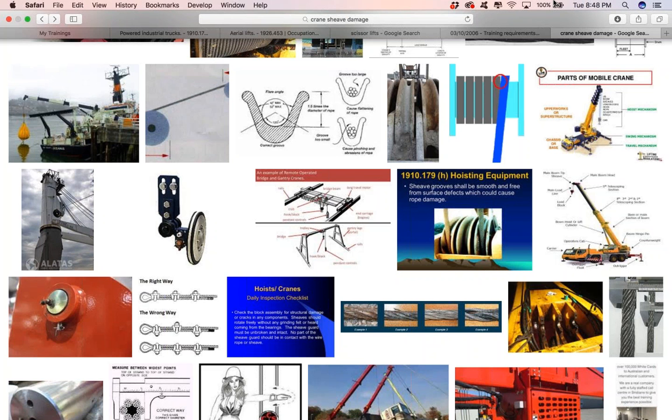Okay, and then it's got to be hands free for the operator. So the operator has got to be able to listen hands free. They can talk and push the button if they have to, but as far as listening, whether it's moving a crane or operating it, the OSHA standard says it's going to have hands free anytime it's being operated, and moving it is part of operating it. And then, of course, the only disadvantage of hand signals is that the person's got to be in sight, like we talked about. But if the operator loses sight of that person, and the only thing they're doing is hand signals, then we have to stop operations.